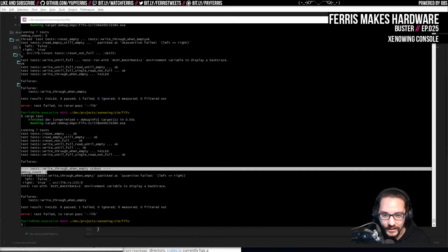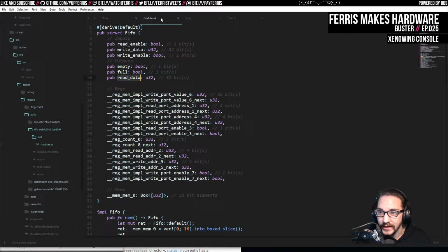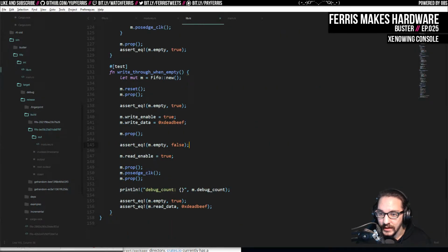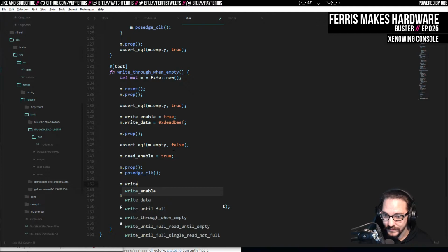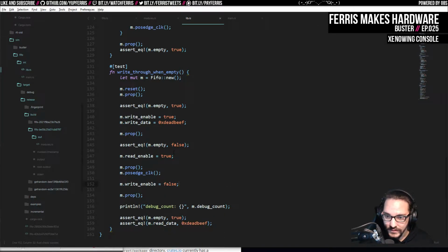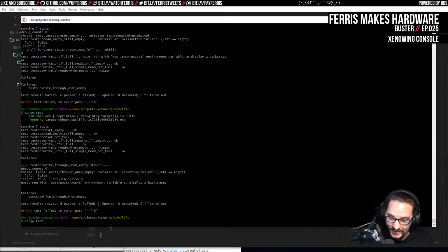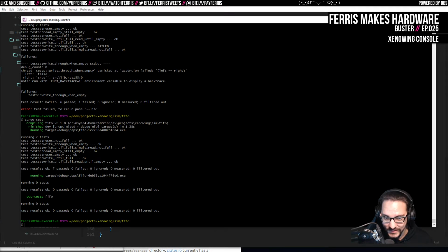Oh, I think I know why. I think I know exactly why. Because I think it's the test that's wrong. The test issues this write and a read. And then on the next cycle, it doesn't deassert the write. So I think if I do this, then it should be empty again. Because it didn't think it was empty because we were still asserting a write. So now the test actually passed. So I feel okay about that.